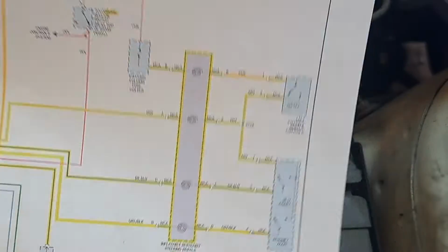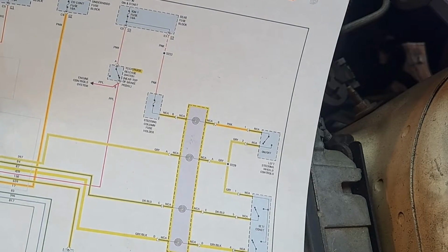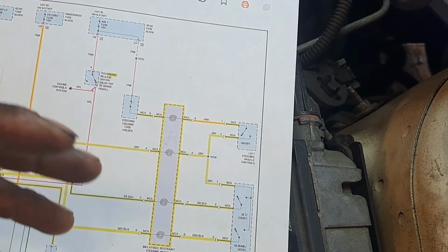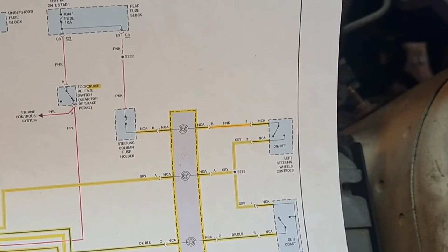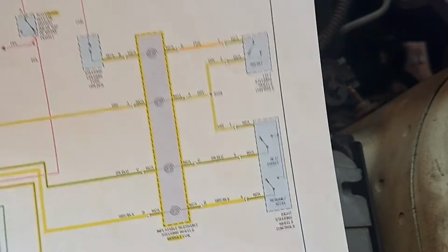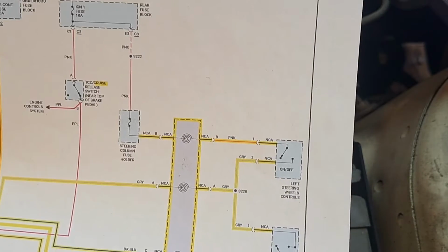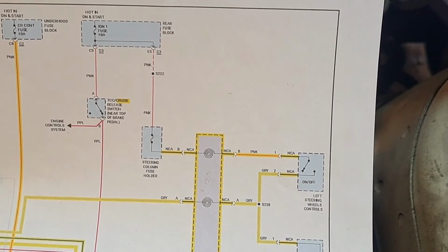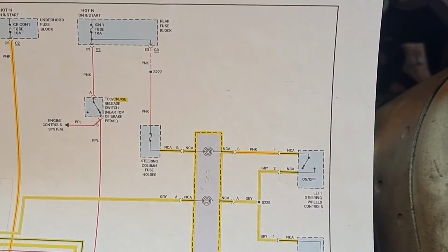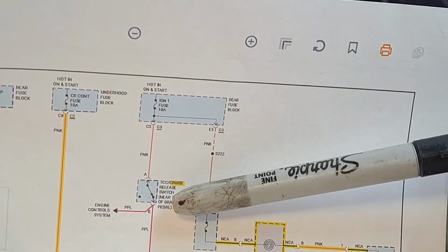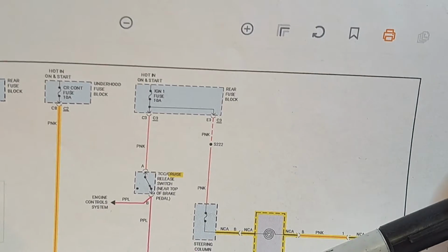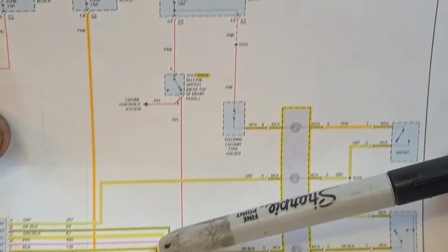Logically, I would want to diagnose this by going right at the airbag. It just seemed like it was a little too much to pull that airbag out, me having to fish for those springs at the steering wheel. So I took another route. So this should be constant 12 volts, just as our brake switch was when we tested that cancel input.